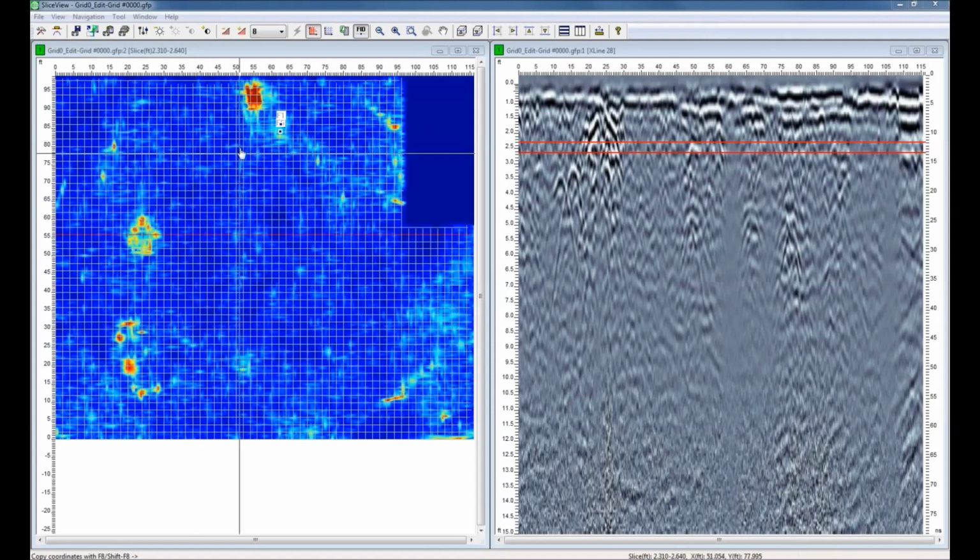Okay, so now you can see I see a lot more in the depth slice. I see a lot more of these subtle reflectors, which is what I'm after. Now, I want you to also remember the quality of the depth slices is affected by the velocity. For the best, most focused depth slices, make sure that you calibrate for the velocity. Now, I'm sure that most of you know how to do this because it's a feature of all our products.